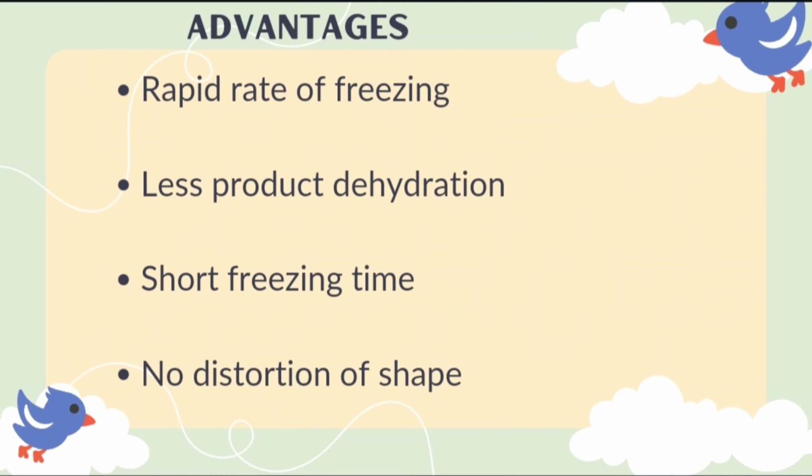The advantages of fluidized bed freezing are rapid rate of freezing, less product dehydration, third is short freezing time, and fourth and last is no distortion of shape. The major disadvantage is that large and non-uniform products cannot be fluidized at reasonable air velocity.